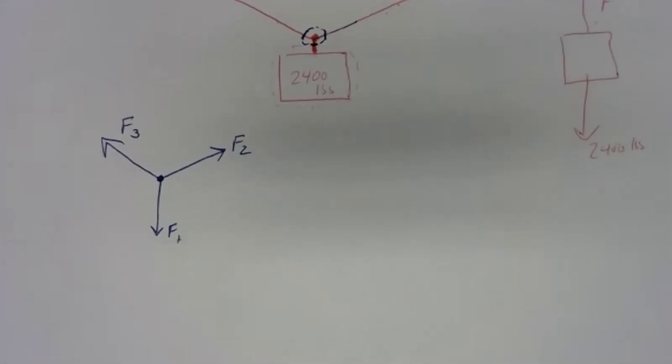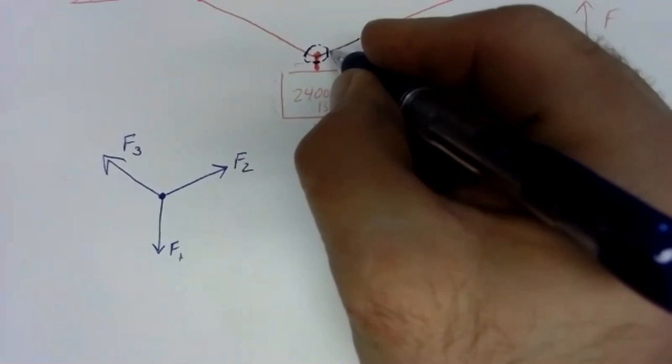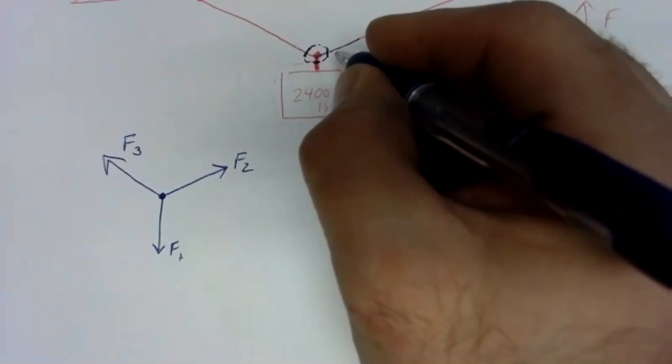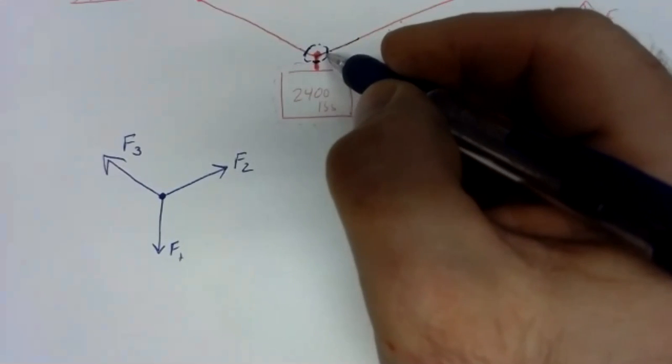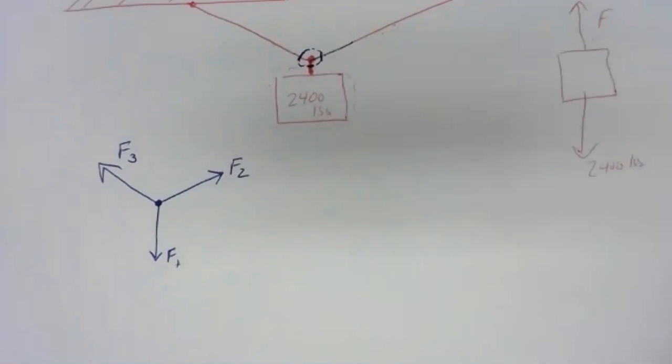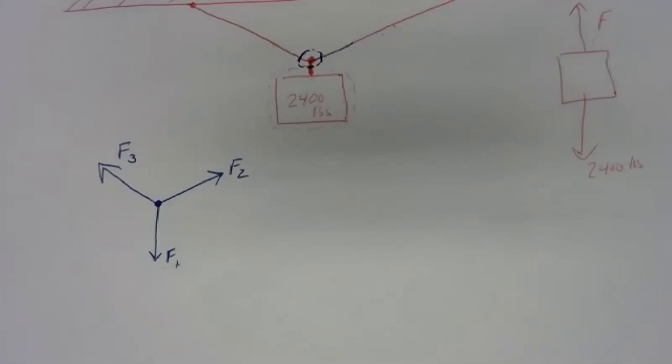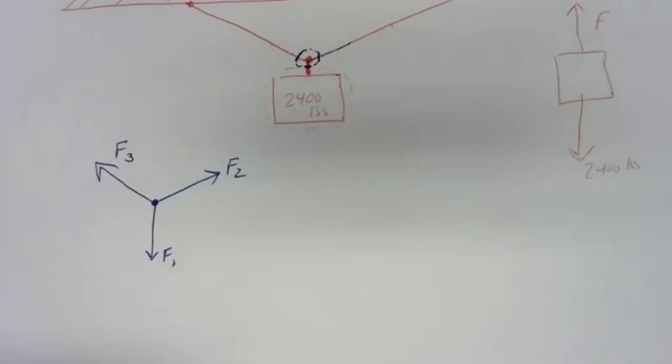But that's another common setup for a free body diagram and how it can be useful to expose what we're interested in. In a sense, you can't calculate what you're interested in unless your system boundary cuts through it, or touches it. There has to be some way to expose in the free body diagram the unknown force that you're interested in figuring out. And the whole point of these problems is to figure out unknown forces, figure out how much force is applied on some of these supporting mechanisms.